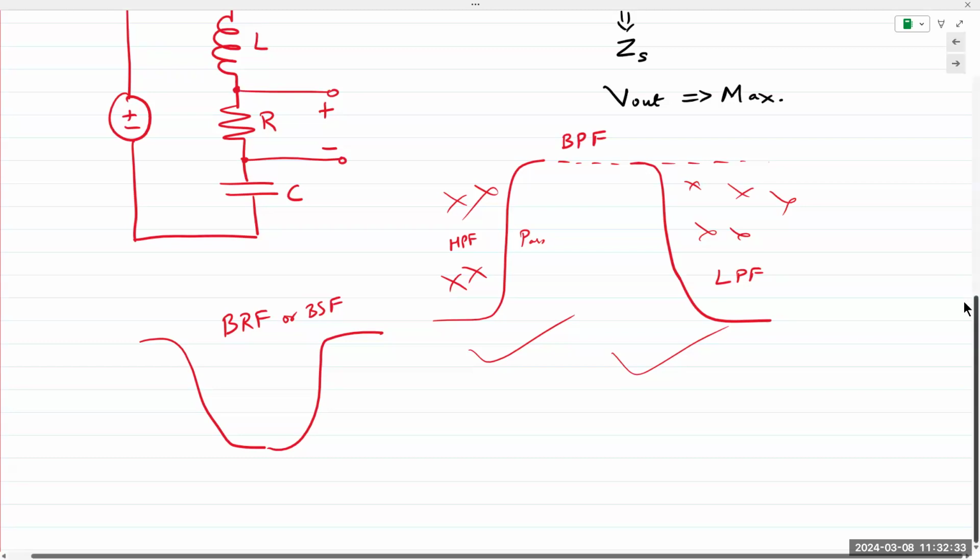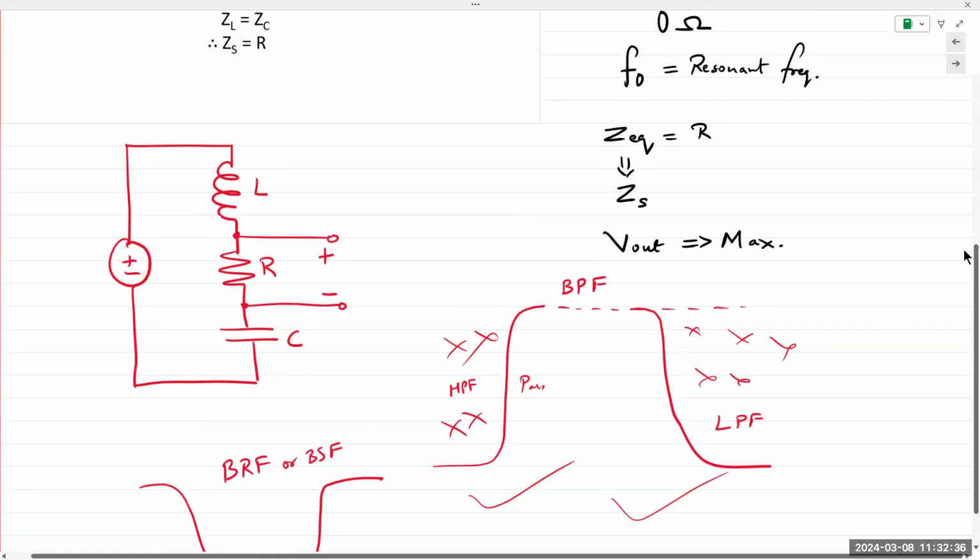Yes, this will be a narrow band of frequencies that will be blocked. Absolutely. A certain use case for that kind of filter would be a notch filter, like a 60 hertz line filter. Your power outlets are at 60 hertz. So if they interfere with your circuit, then you can install a line filter that will block out that 60 hertz signal, so it would not interfere with your circuit. That is where you want to reject a narrow band of frequencies, but you want everything else to come into your circuit.